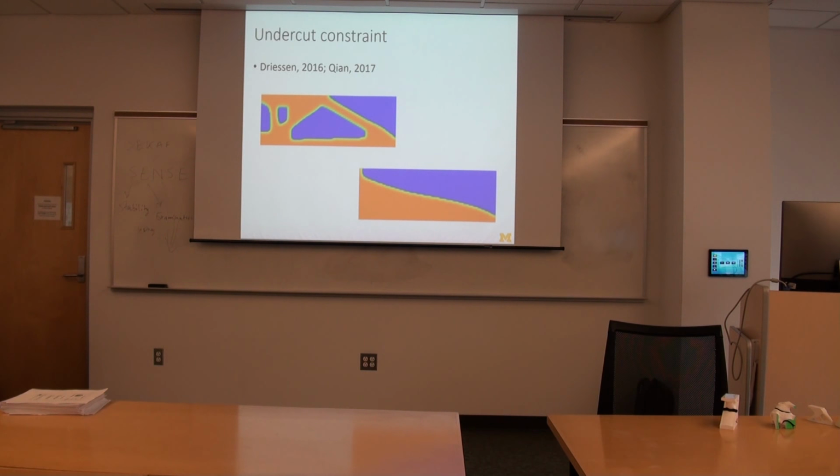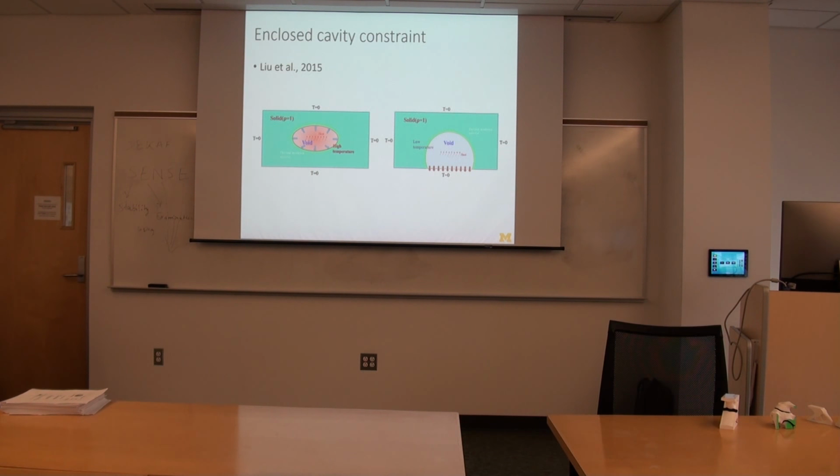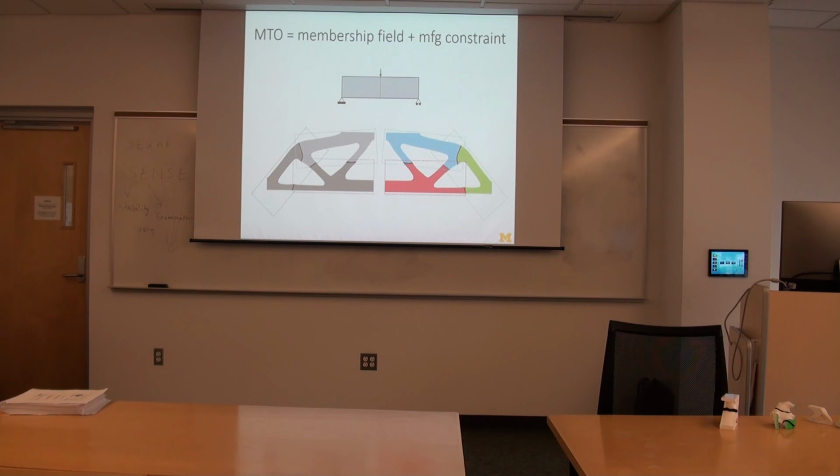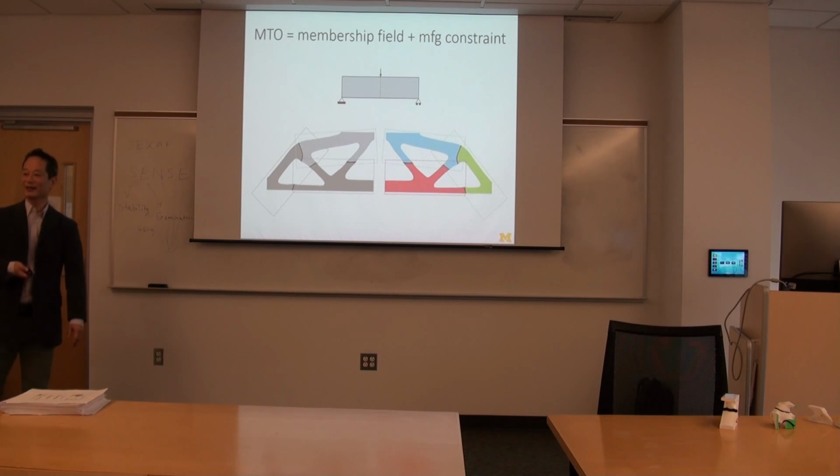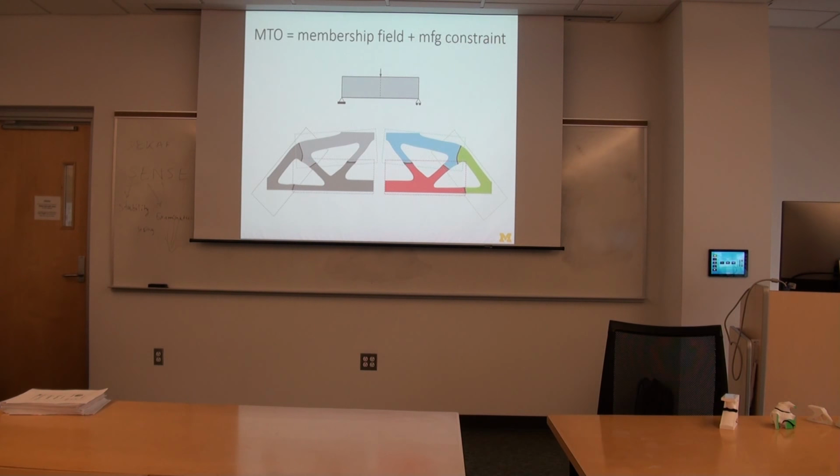And then why use topology optimization in the first place? That's the question. Again, this will give a good comeback if you consider multiple pieces. Indeed, yes. So things could look like this. This is a size and cavity constraint applied. So the individual piece is cavity free, but the size is also confined so that it will stay within the prescribed, say in this case, the printer size. And boundaries are created so that they will be joined in the least impact portion in the structural map.